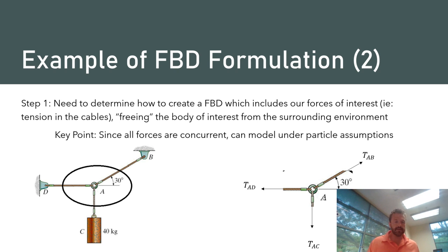So that kind of reduces the unknowns associated with that particular, let's start with T_AD. We know the direction, but we don't know the magnitude. So we have one unknown there. In addition, I'm going to skip around a little bit and go to the force exerted by cable AB. If you notice in this scenario, we know that it's inclined 30 degrees from the horizontal. So if we were to know the magnitude, we could decompose it using the known geometry here. So we have one unknown, two unknowns. Are we going to be okay? Well, yeah, it turns out we are, because we actually know the tension in this cable by something that I'll show you here in a minute.